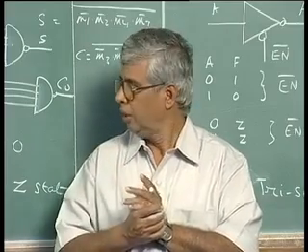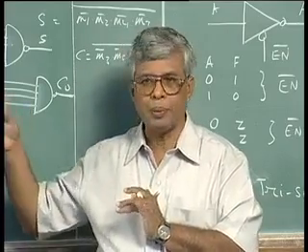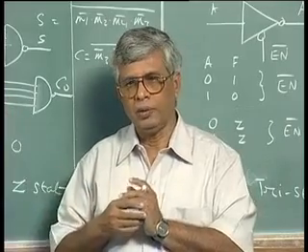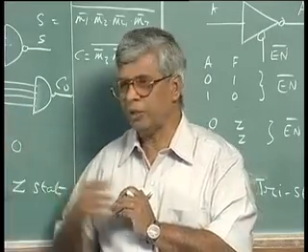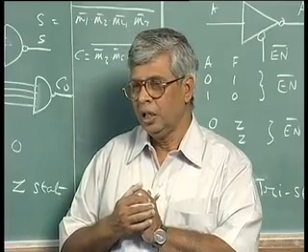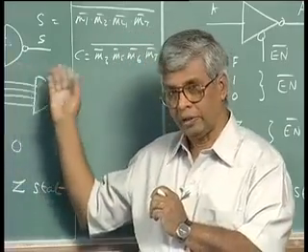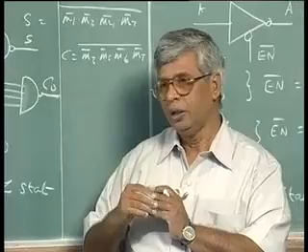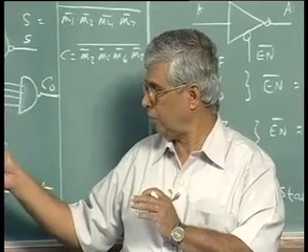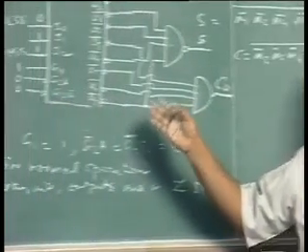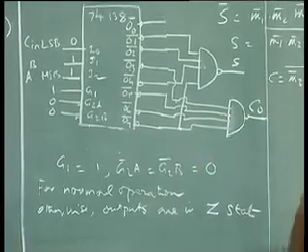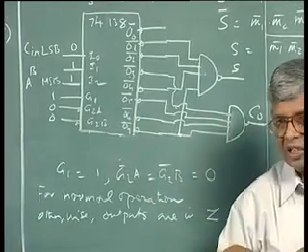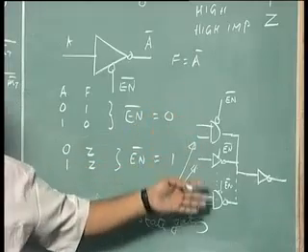Then we talked about mux and decoders as two major components in MSI design, and we talked about how to map a given function, given K-map, into this hardware. We talked about the enable feature and how to get active low and active high outputs, and how enable features control the operation. What happens when the circuit is disabled? It goes into a high impedance state, or high Z state, and this is the idea behind that.